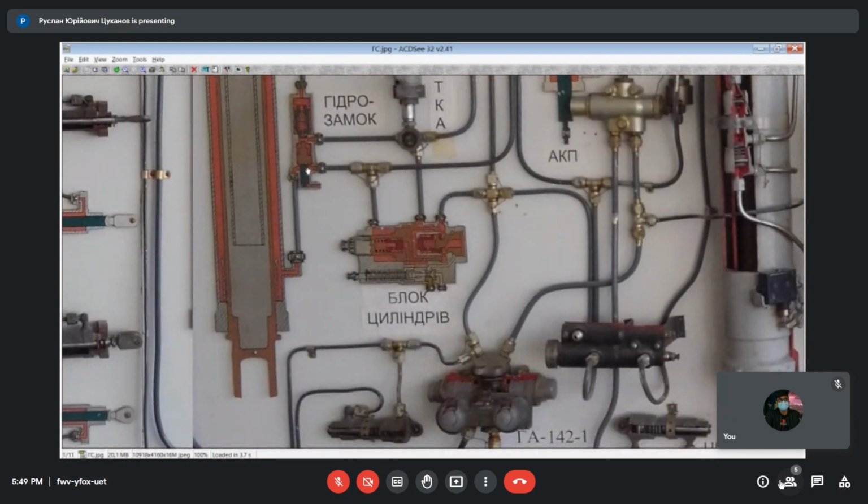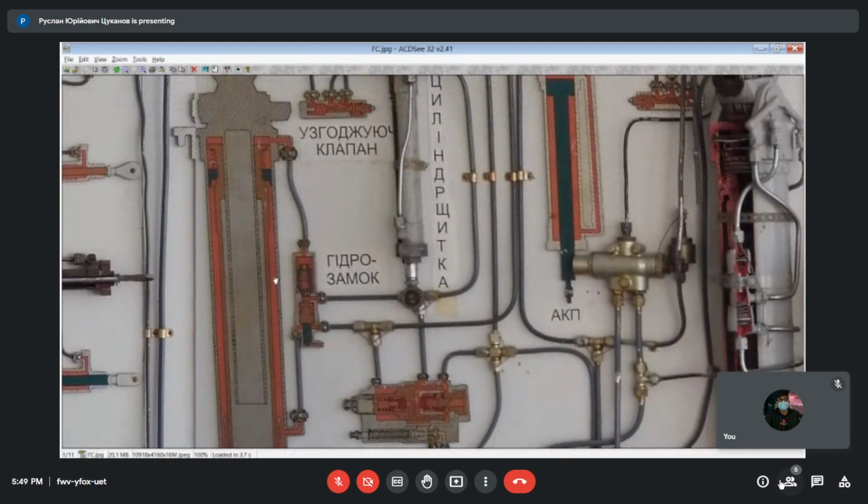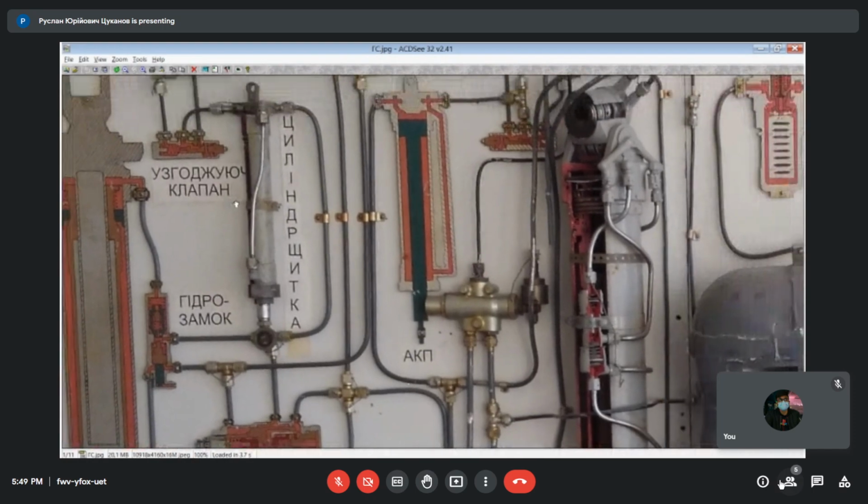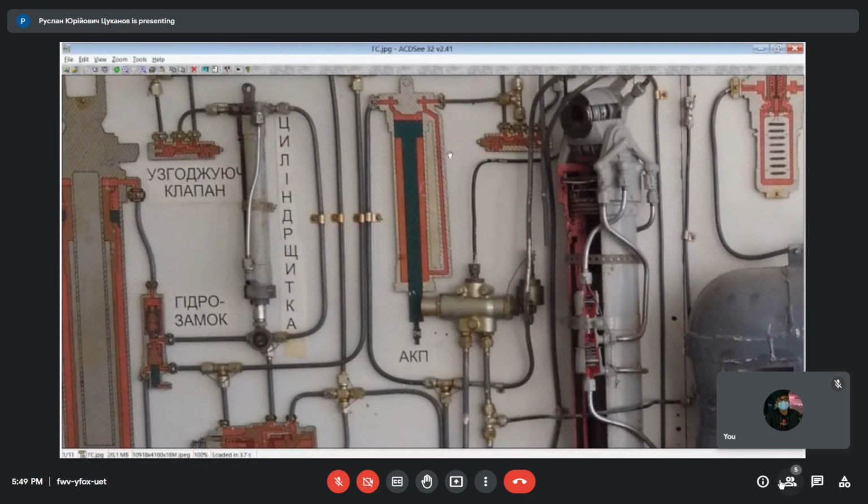It comes to the retraction cavity of the landing gear actuators, opens the mechanical locks which are inside the actuators, and begins to retract the landing gear. When the landing gear is retracted, it will mechanically press the sequence valve, and only after this do they allow the sequence valve to pass the fluid to these actuators to retract the jaws, closing the jaws of the landing gear legs.